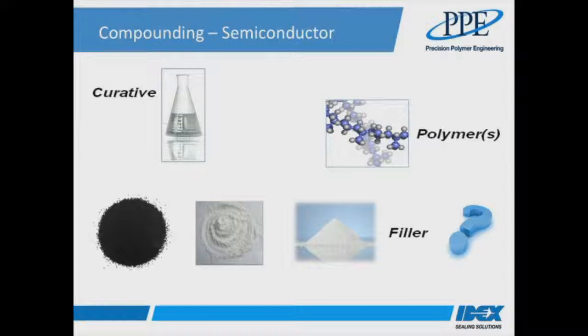An alternative reinforcement system to carbon black is shown in some of the other images. Silica or silicon dioxide is often used, but again there are different types of silica materials. Silica is a naturally occurring material, however natural silicas have a number of impurities including metal oxides and other inorganic compounds, and the level of impurities are relatively uncontrolled. A better option for semiconductor applications in order to avoid metallic impurity contamination is to use synthetically manufactured silica, which has typical purity levels of greater than 99.9%.